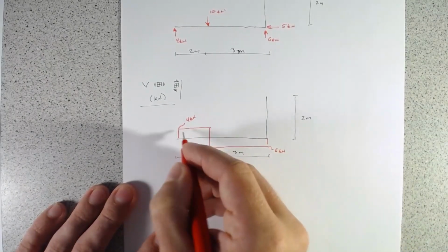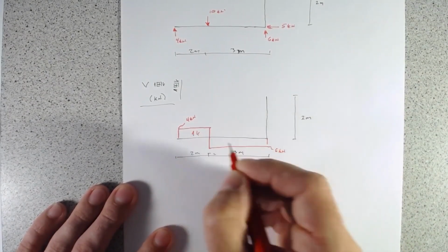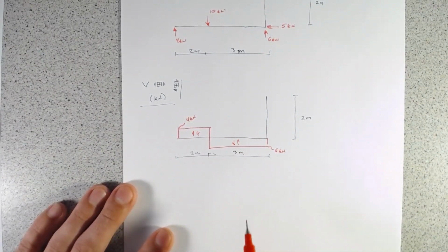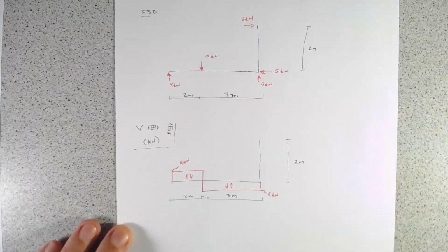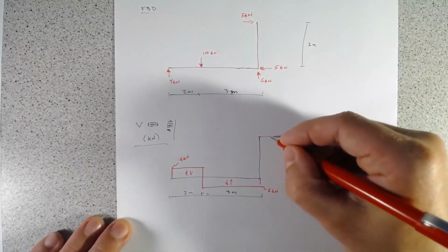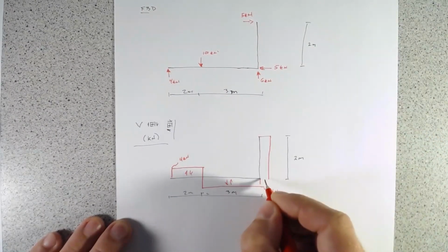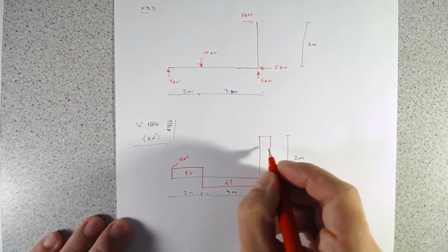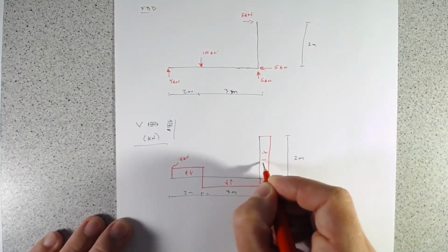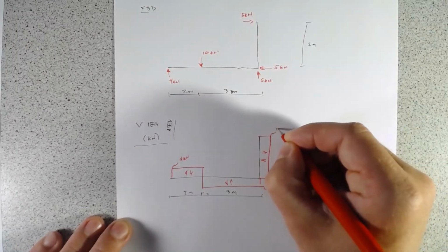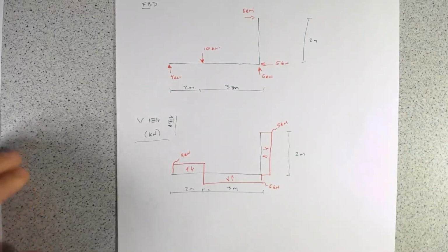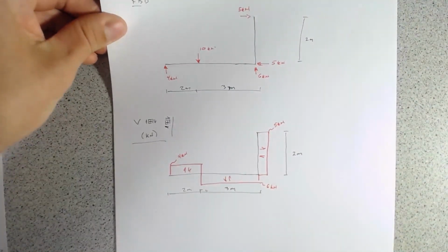We are in equilibrium, and I will put just the direction of the shear on the diagram just to be explicit. And then up here at the top, we are going over 5 kilonewtons until we come down and come back in 5 kilonewtons. So that all makes sense, and it's a pretty straightforward shear force diagram to draw.